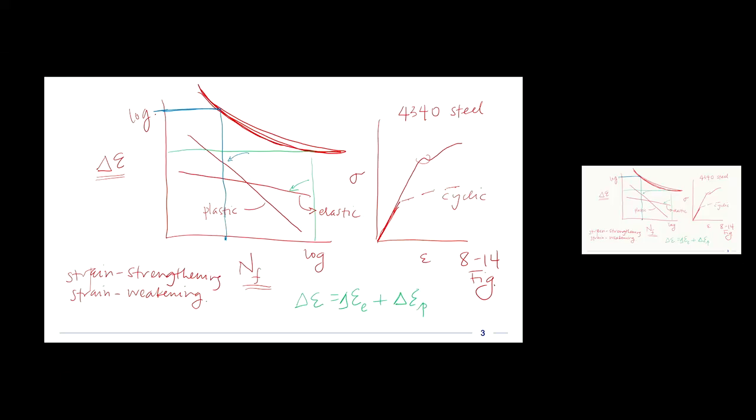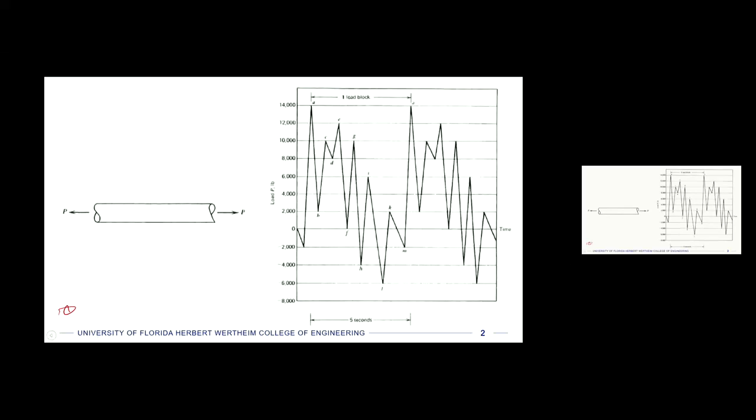And now we're going to use it for an interesting example problem at the end of the chapter. The reason it's interesting is that it has a component here that's supposed to last for a grand total of 15 minutes. That's a very short time, which means probably low cycle, so we have to look at the fatigue.